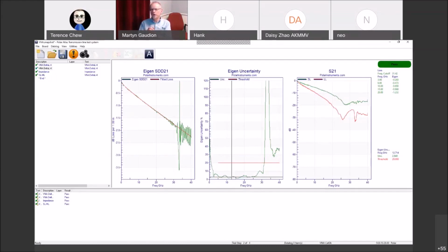So the only way you can extract total loss and turn that back into roughness, copper loss, dielectric loss is by mixing the modeling and the measurement, by putting the measurement numbers back into the field solver and comparing and contrasting the results. Once you've figured the model, the measured, and the mechanical measurements, then you can have a very good understanding of what's driving the levels of insertion loss in your PCB.